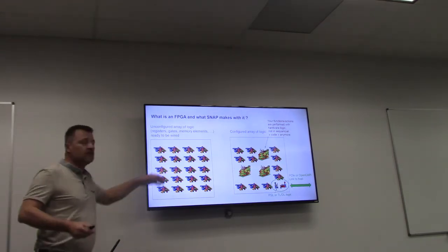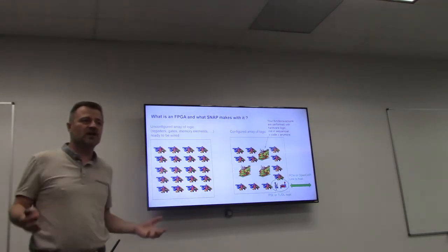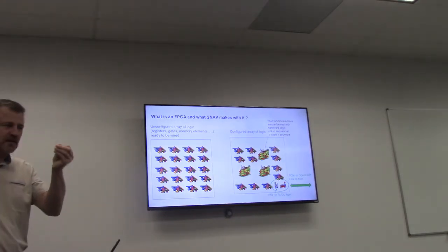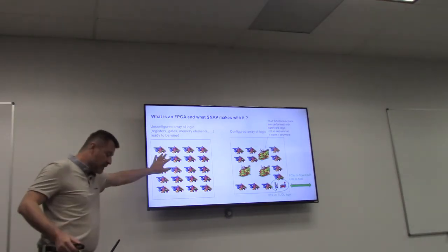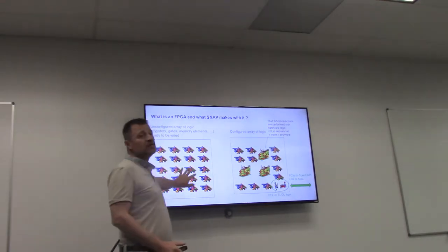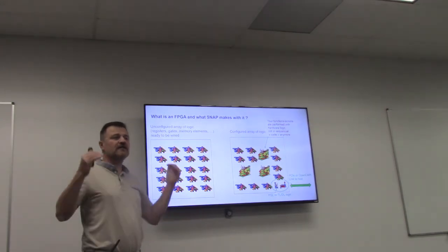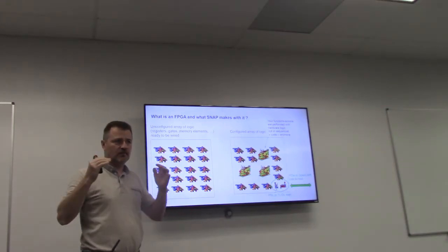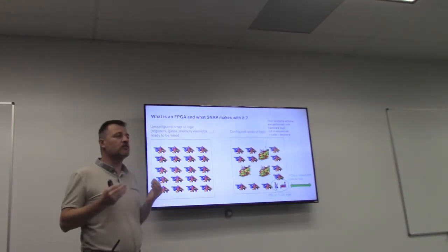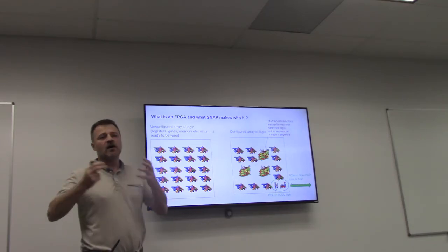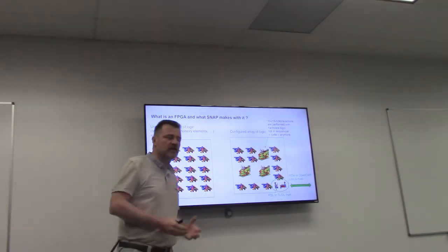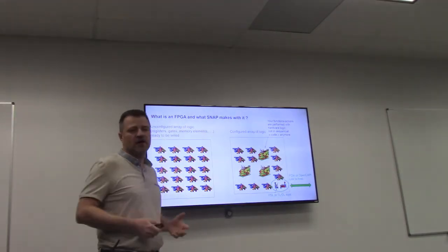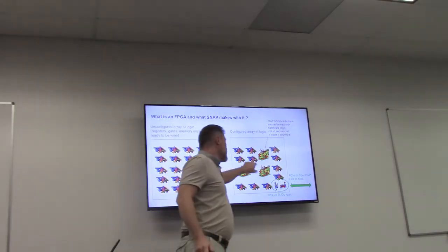For an FPGA, you get a sea of gates, a sea of logic, a sea of registers, a sea of flip-flops, a sea of pieces of memory that are not interconnected. Then you need to describe what you want to do with this sea of gates. So it's like an ASIC that has not been finalized with all the routing. It's up to you to decide how you want to route the logic to make a small microprocessor. If you want to embed an ARM inside, you need to describe how your registers are connected to make your accumulator and so on. Once you have described that, you make functions.